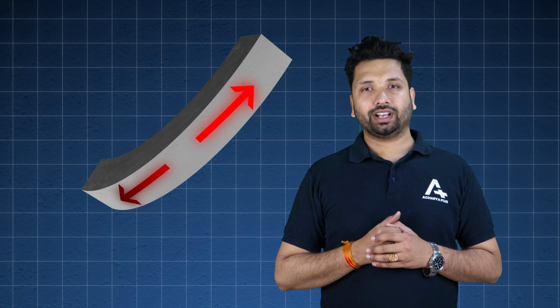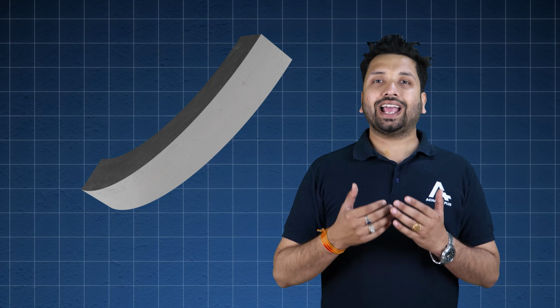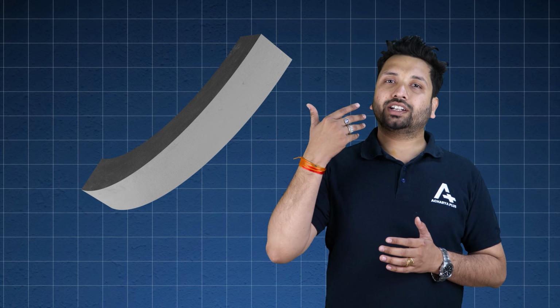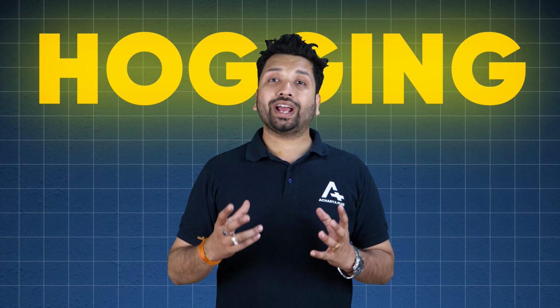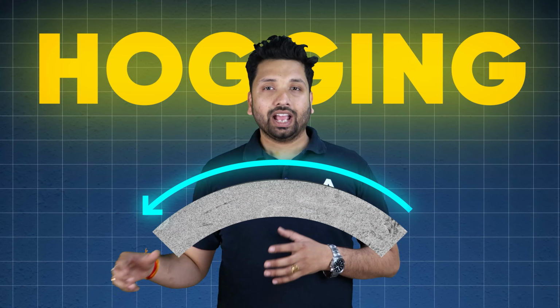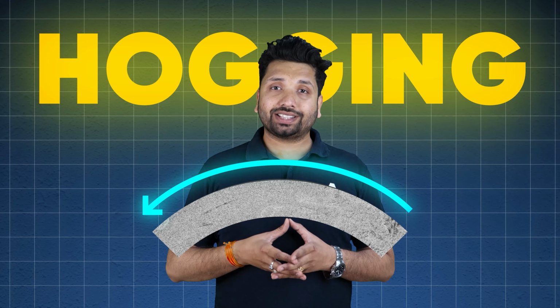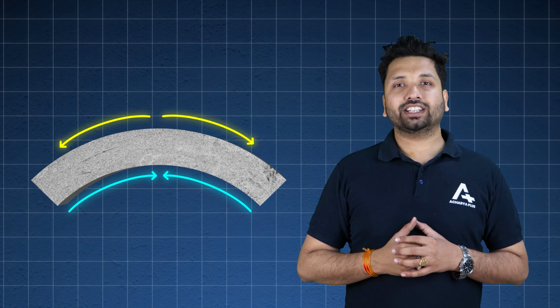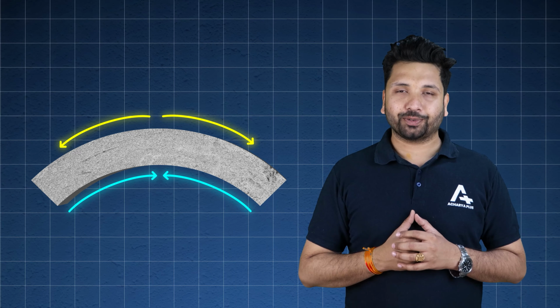the bottom fiber. You can talk about stress and strain of compressive and tensile nature on the top and the bottom fibers respectively. Now the second type, which is hogging. When a beam is subjected to hogging, it bends like this. Here the nature of stress and strain on the top fiber is tensile and in the bottom fiber it's compressive.